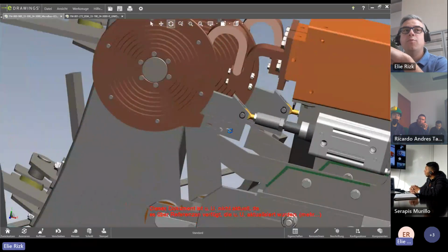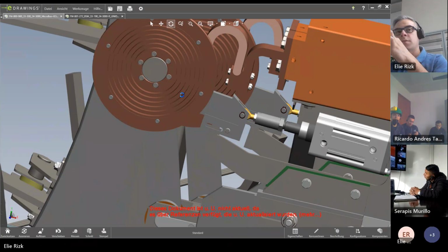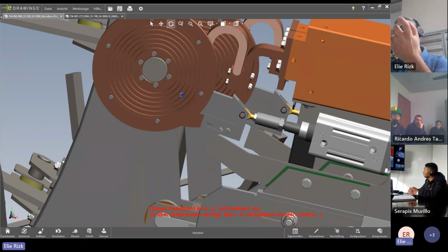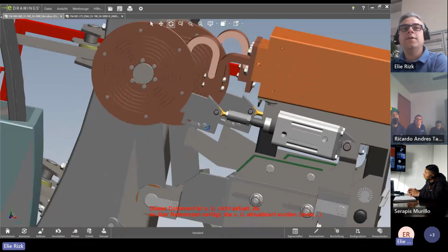You will have too much gap here when this roller is closed, because 10 to 10, so you have around 2 centimeters, let's say. But then when you move to 5 to 5, you have in total 1 centimeter. So you have a big difference between the two wires, and you get a little more gap here. So if you adjusted this arm mechanically to be a little more back, then when you move to the smaller diameter of the wire, you don't have enough contact with the welding angle.